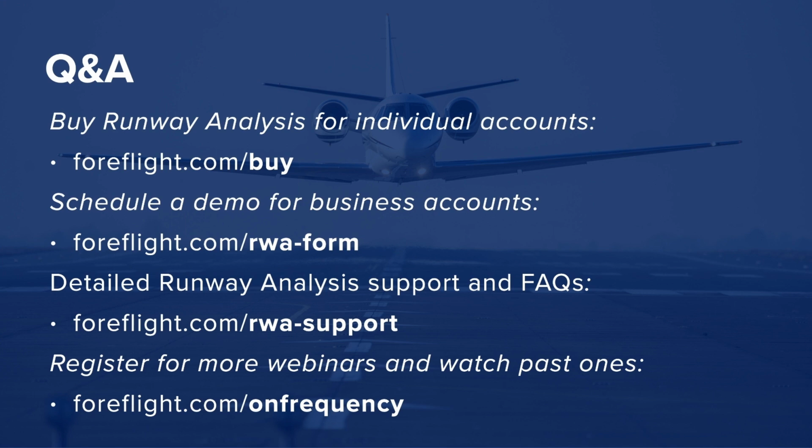By the time you've lost an engine, the pilot's going to declare an emergency. Air traffic control is going to get on their landline and, say you're departing Long Beach, they're going to tell Torrance, stop all departures, or LAX, stop all arrivals, whatever is necessary. So once a pilot has declared an emergency, airspace should probably be the least of their concerns. Air traffic control is going to take care of that for you. So our goal is safety, not avoiding airspace. But of course, we're going to keep in mind, when there's absolutely critical airspace that you should not penetrate, our procedures are not going to go through that.